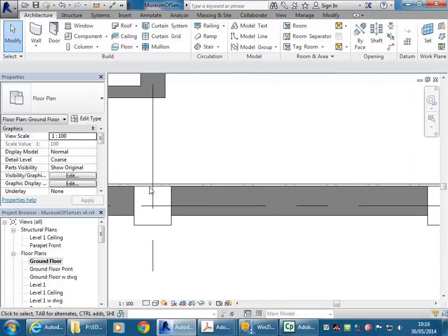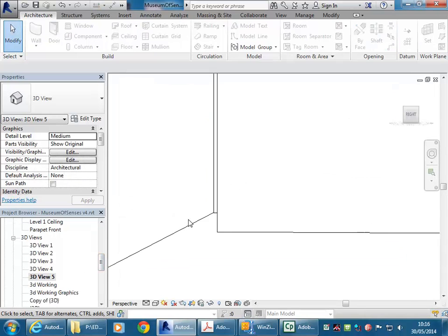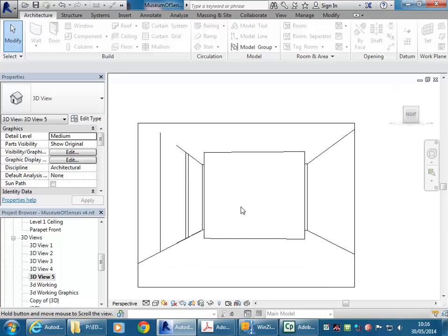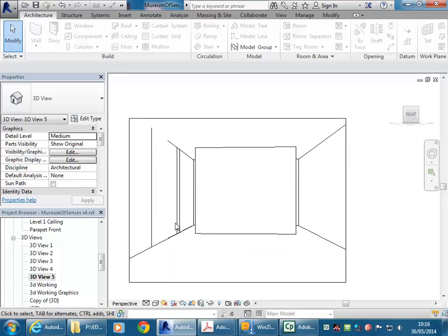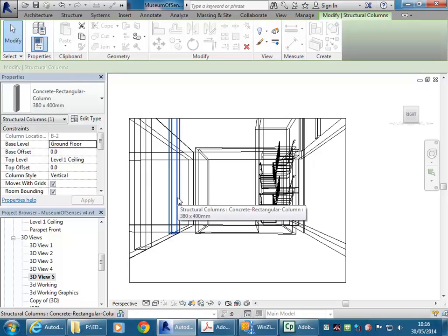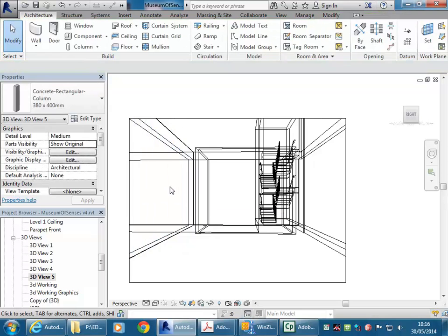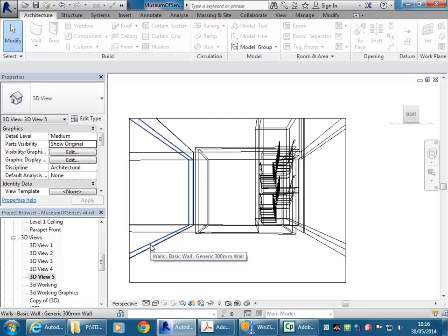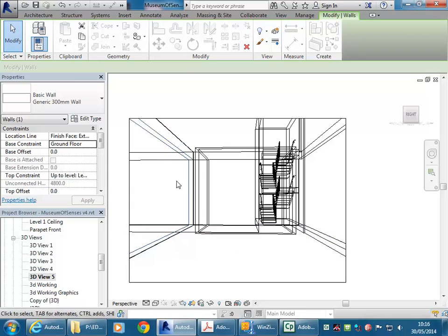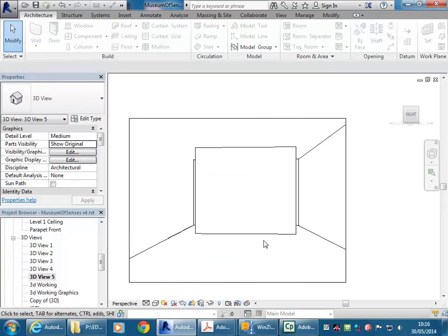So just using again a new wall. So back in my perspective, now I can see that as a single surface, which is what I want. You can still see the lines coming through from the columns. So I'm going to go to wireframe. It won't print with those, but to take them out of this view and just make sure they won't interfere, I'm going to use VH with one selected, which is view hide, and then the wall behind my lining, I'm going to select it and then right click, hide in view elements. So for rendering, it helps to have the view set up as cleanly as you can.